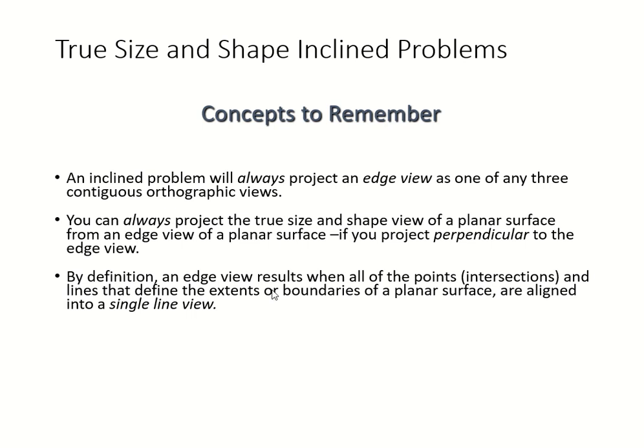So every time you think about the edge view, just remember it looks like a line, yeah, a single line. Don't forget, to make the edge view, the lines going through the points on a plane are parallel to your line of sight, okay?